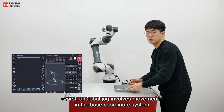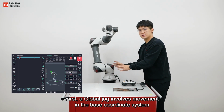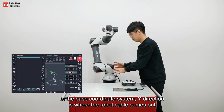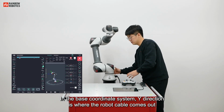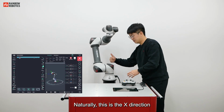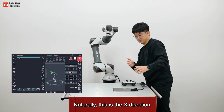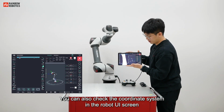First, a global jog involves movement in the base coordinate system. In the base coordinate system, the Y direction is where the robot cable comes out. The Z direction is the vertical direction. Naturally, this is the X direction. You can also check the coordinate system in the robot UI screen.